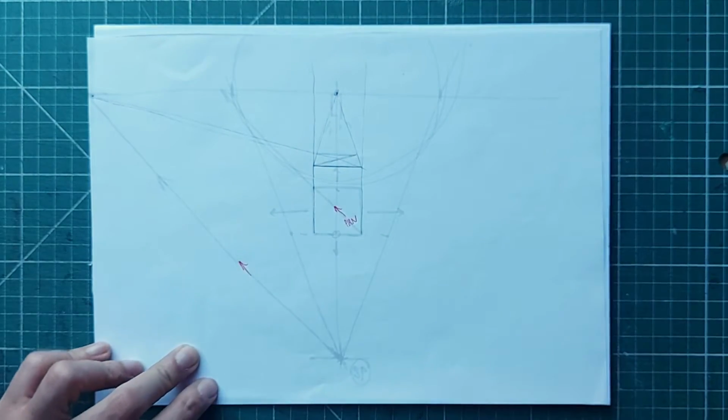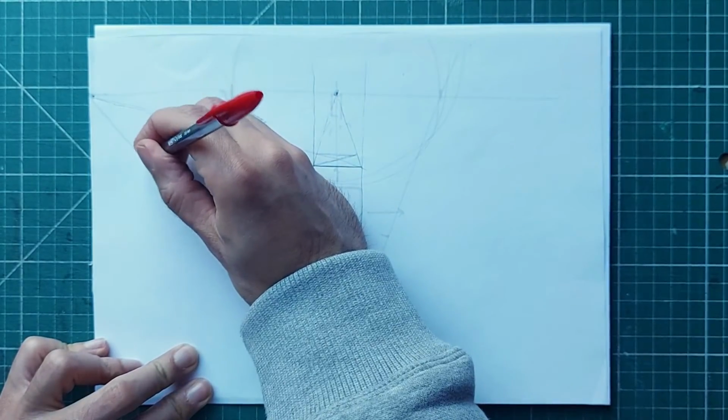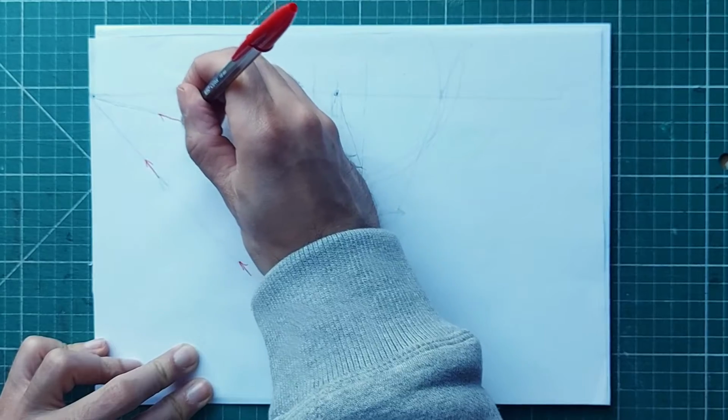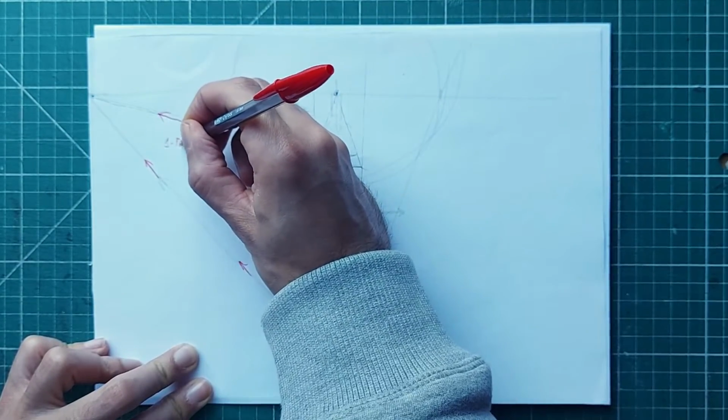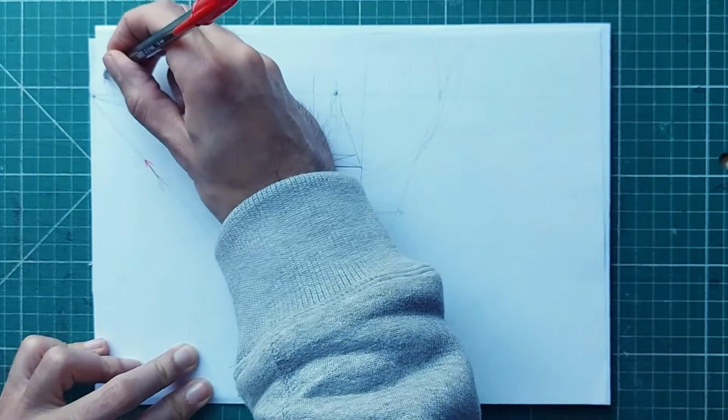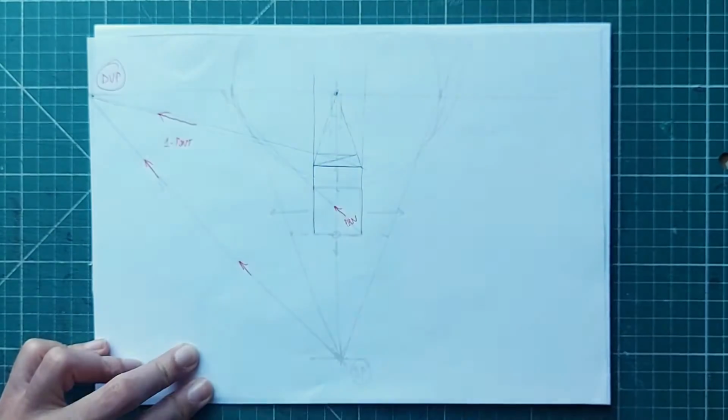Note how in plan view, the 45-degree lines running from us and the cube were parallel, but here they project to the same spot on the horizon. This is the only thing you have to change when you convert from plan to perspective, and it's a great rule to know. Parallel lines in plan view converge at the same spot on the horizon line in perspective view.